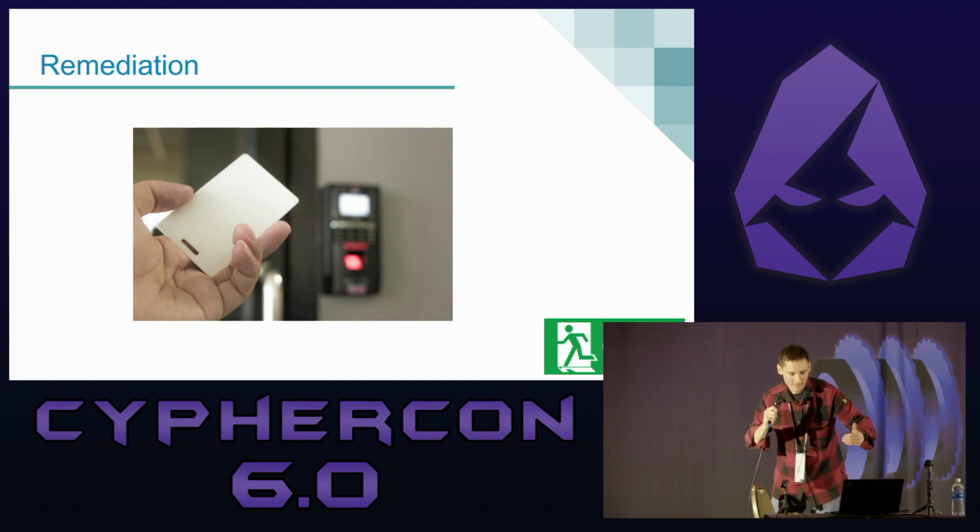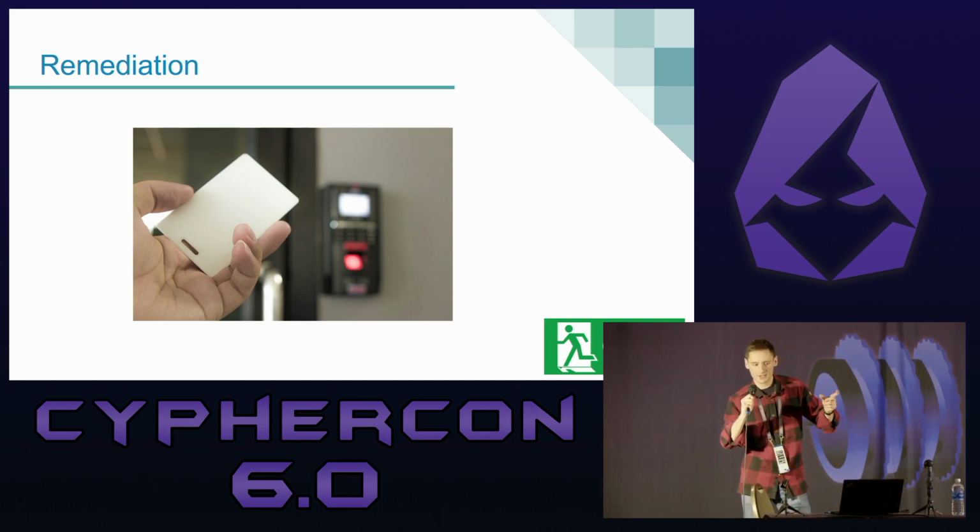next to the door. There are also some dual technology REX sensors that use both passive IR and radar to identify if there's actually someone on the secure side. They're pretty cool. They're more expensive though.